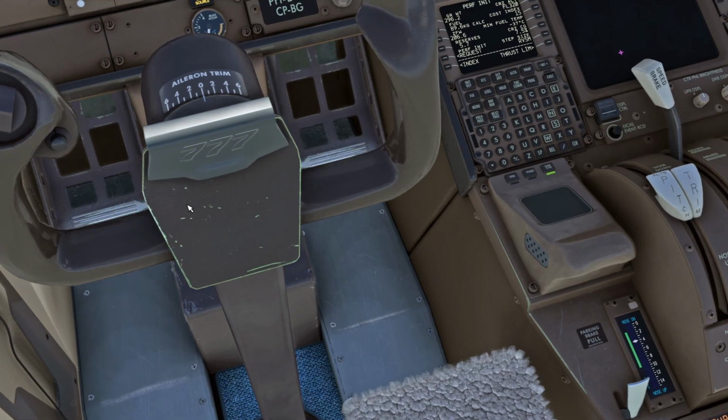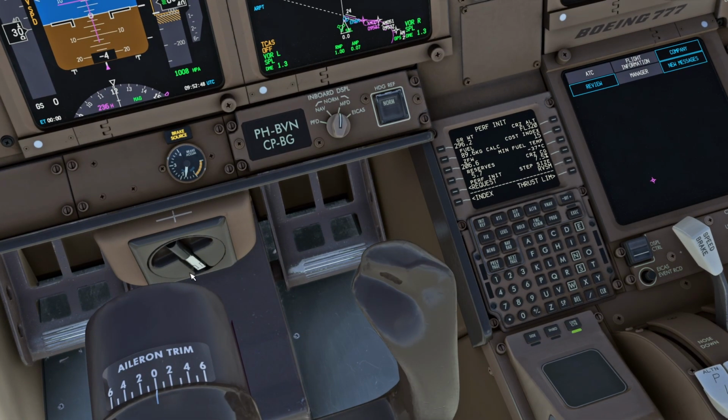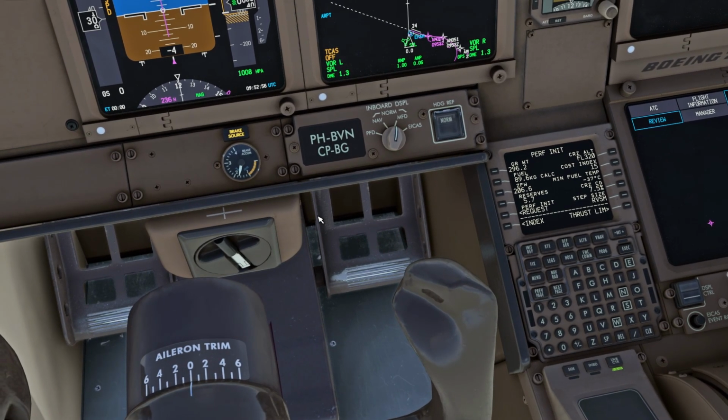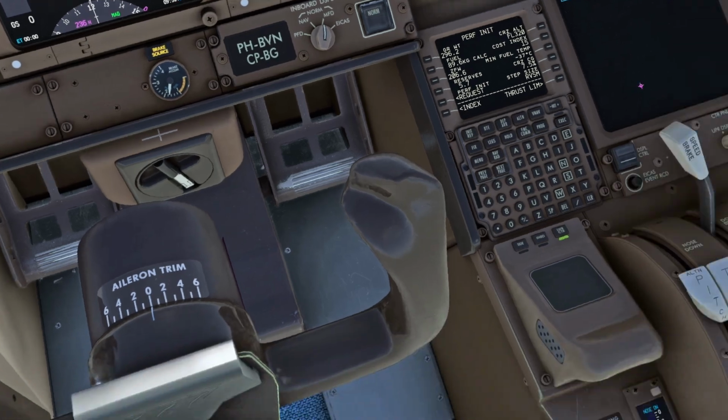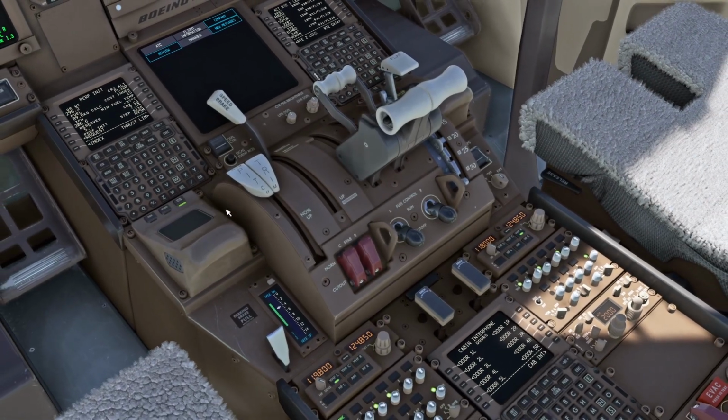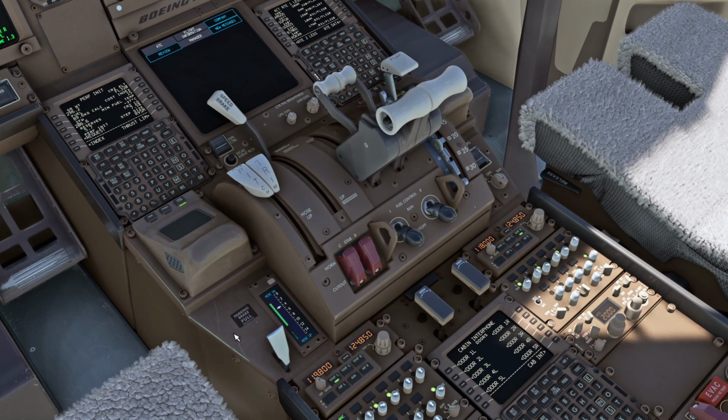In some situations your brake accumulator might be a little bit low. In that case you would have to contact ground personnel to ask if the bypass pin is inserted, and then you can pressurize some of the hydraulics to build up some pressure, but in this case the parking brake is correctly set. Then let's get back in the flow. We went this way and we set the parking brake.